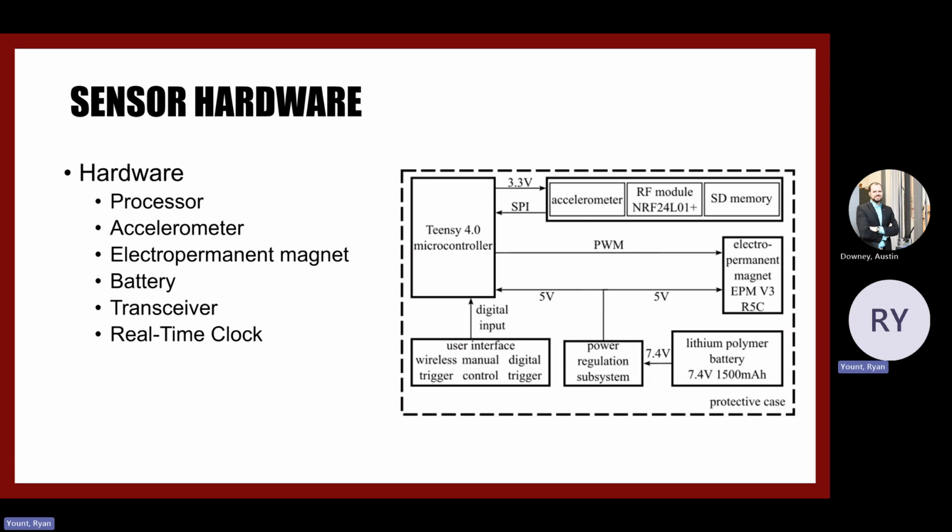And that works with a pulse width modulation for attaching and detaching the magnet, and then working through the serial peripheral interface for all the other components like the accelerometer, the RF transceiver, the SD memory, and the RTC as well.